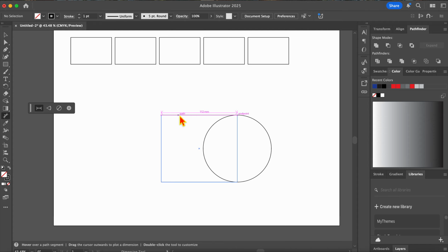So it will hover over and give you the measurements, or if we click on the two of them, it'll tell us that that's 100. I've got mine set to no decimals, which is why it didn't give me a funny number there. Now it's telling me that it's 100mm there, and then you can just select that and delete that if you wish.